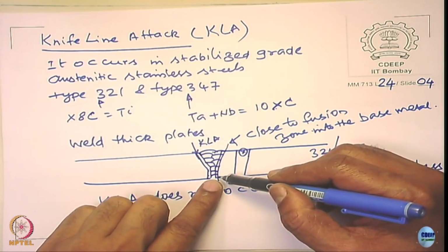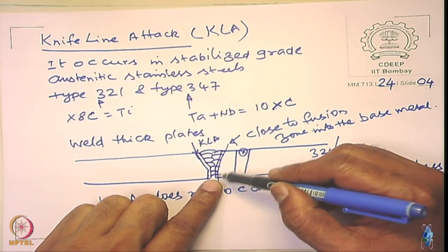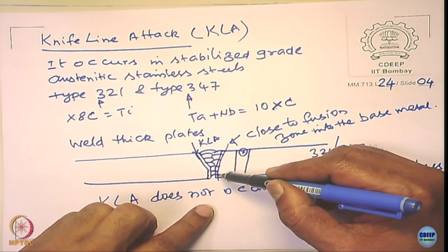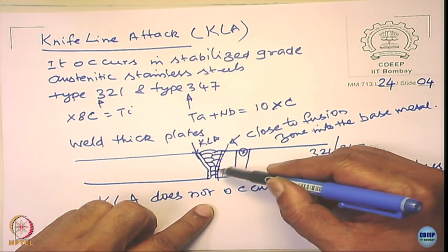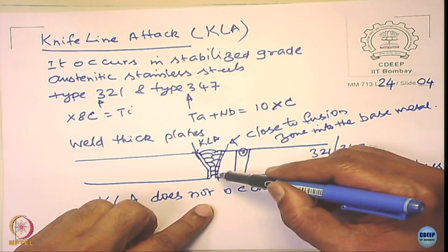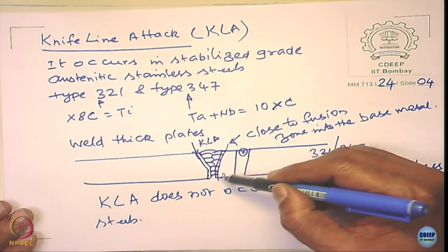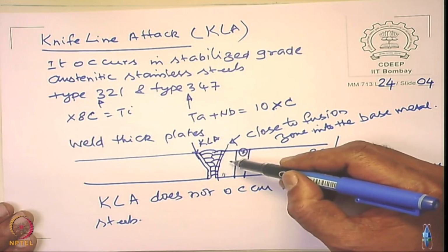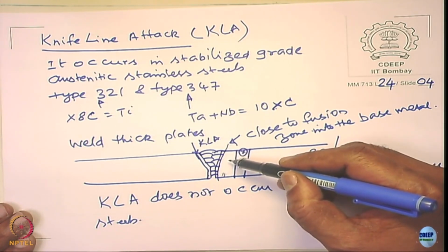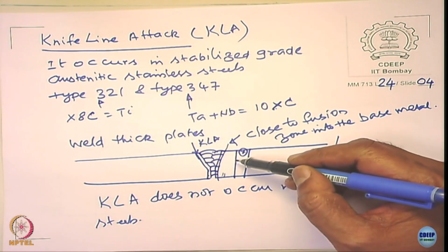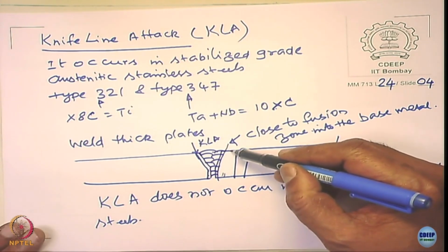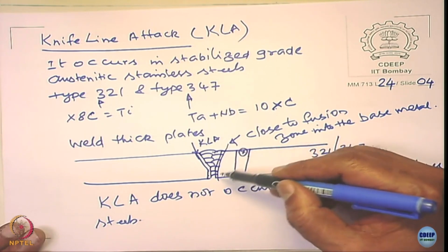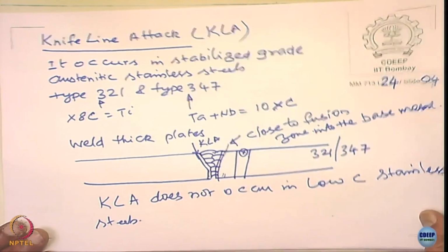the lower one becomes the reheated zone for the upper ones, and so the chromium carbide starts forming. So these places the chromium carbide starts forming. When the chromium carbide starts forming, then you get sensitization, and that is why it is very close to this. Please notice, if you move away from it, if the temperature is lower than 1200, nothing happens. Titanium carbide is still stable. So that means you are not going to get any sensitization here nor here, and you get it only very close to this. Okay, so that is the reason why it happens.